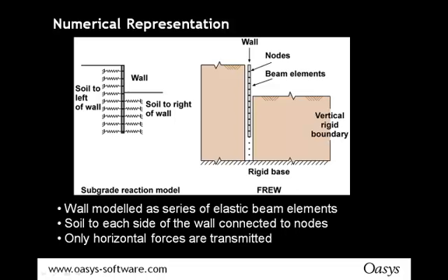So it works by initializing the in situ ground stresses. It models the stiffness of the structure and ground, and then movement is generated until the out of balance forces come into equilibrium, and it then checks the stability of the wall, and it looks at the wall load effects and prop forces and calculates them, and then the wall and soil deformations are calculated accordingly. So that's just a rundown, almost step by step, of how it works.